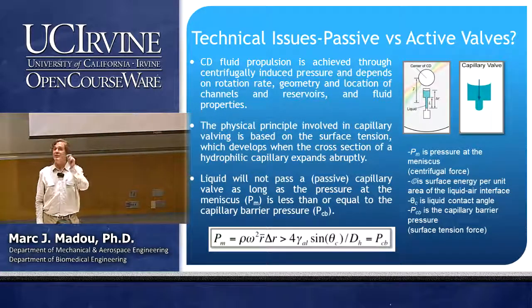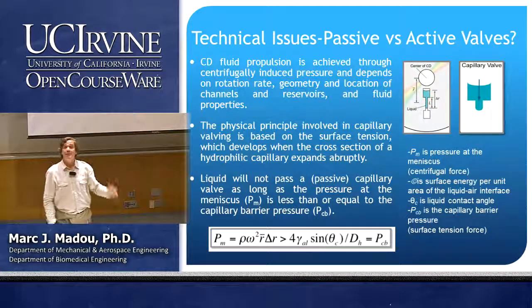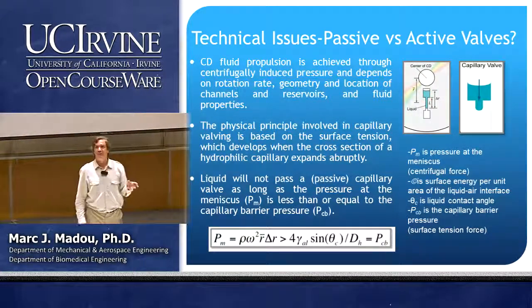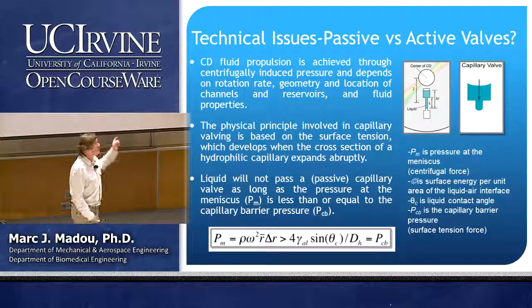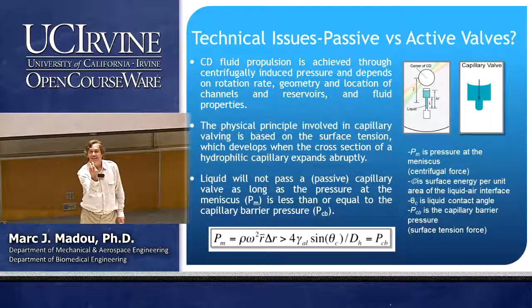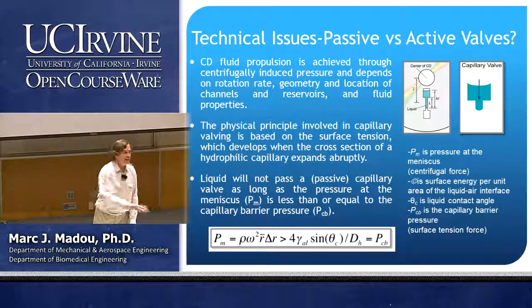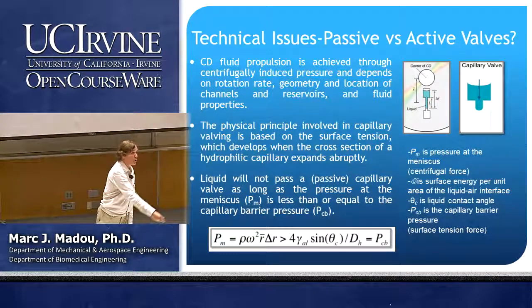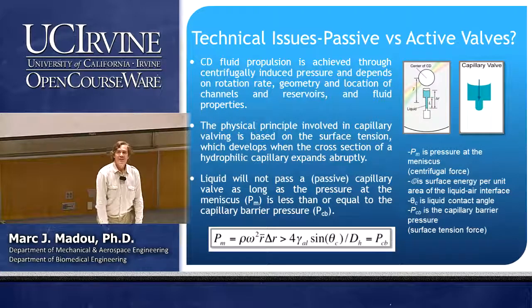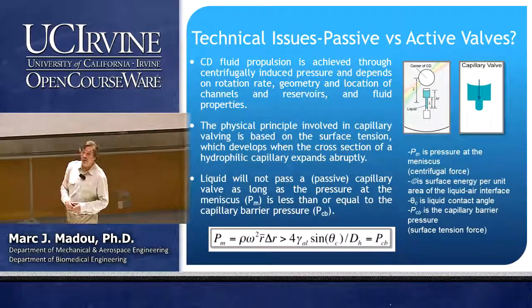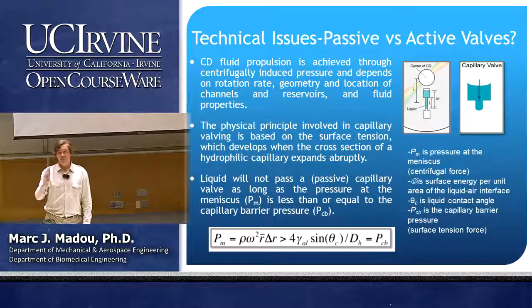And by the way, make it such that the valve doesn't require any energy to stay closed. Give you an example. We have often worked with ice valves. What is that? Well, I put a cooling element underneath this capillary and I make the liquid plug ice. Nothing will go through it, right? But I need to keep this thing cold. And so I keep on spending energy. That's not too cute, is it? So we need to develop a valve that's normally closed but does not need any energy to be closed. If you understand that, you understood that little cartoon there on the right.